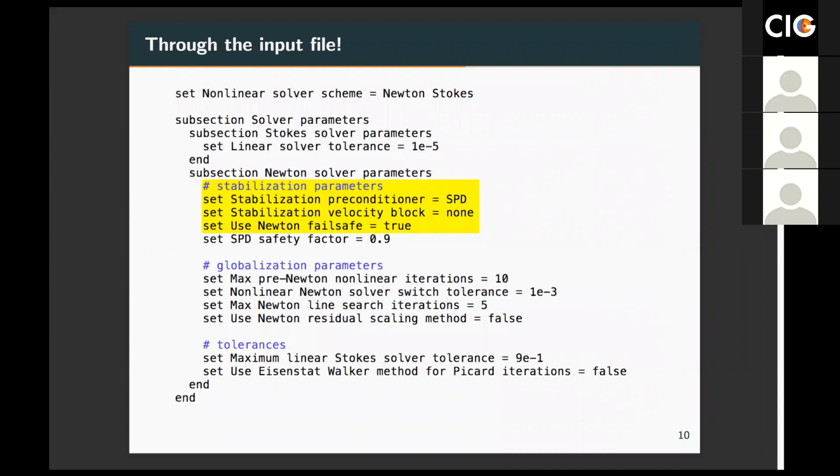So what you can do is use the unstabilized version of the Newton solver, and when the linear solver crashes, you can set a failsafe, this failsafe option here, that automatically turns on the stabilization for the rest of the time step. It will start again at the point it left and continue converging until the new time step, and then it will reset itself to the previous values.